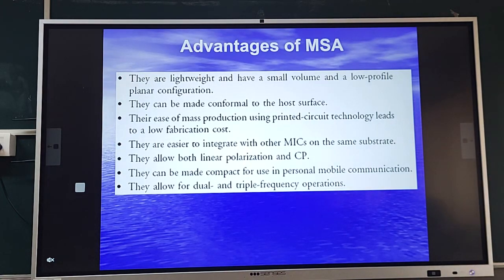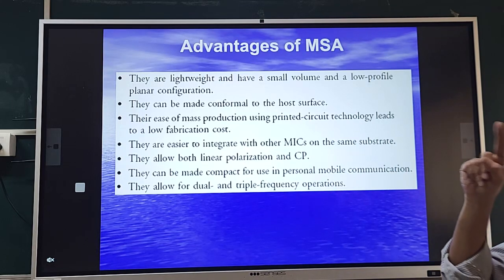Now, if I use a fixed frequency antenna over there, or if I use a dipole or any other variations over there, then I need to either change the design and integrate multiple antennas to have access to multiple frequency bands. So there, microstrip antenna comes to the rescue. A single radiating patch, again as I said earlier for the circular polarized case, with suitable modifications can provide this multiple frequency operation.